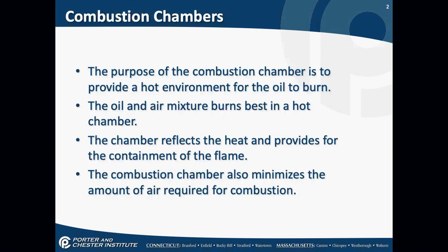So the purpose of the combustion chamber basically is just to provide a hot environment for oil to burn. The air and oil mixture burns best in the hot chamber. The chamber reflects the heat and provides for the containment of the flame. The combustion chamber also minimizes the amount of air for combustion. Let's see if I can give you a picture, or describe a picture, of why this is important.